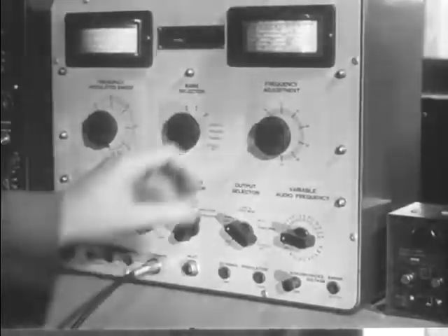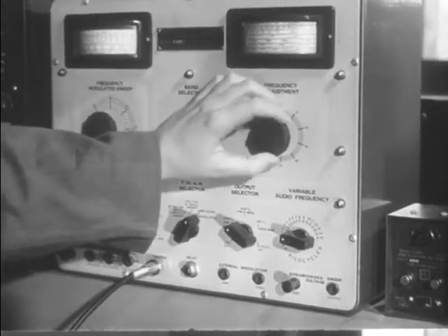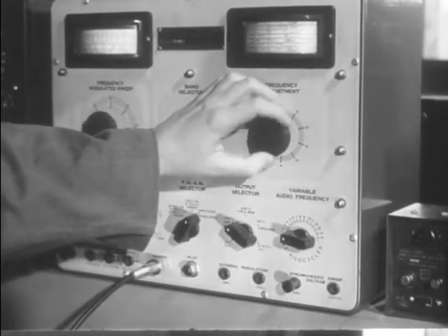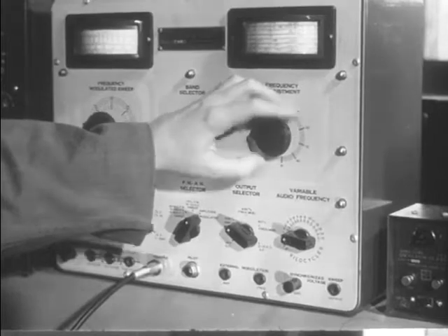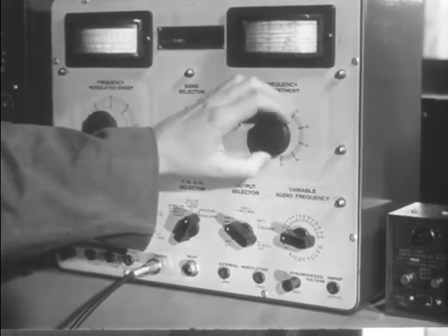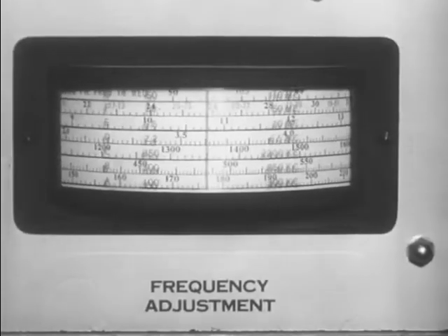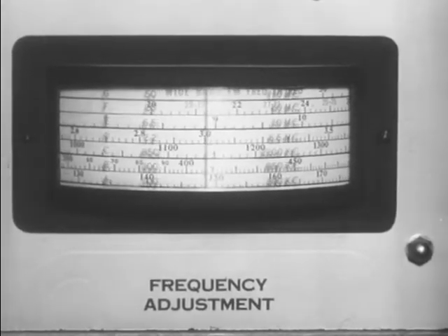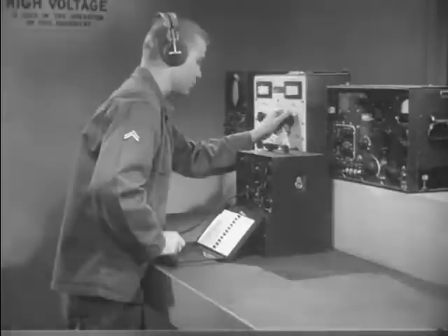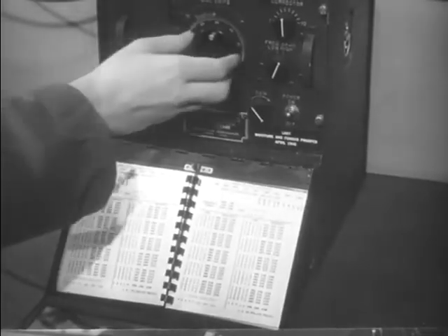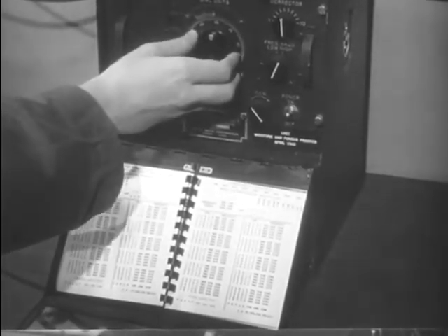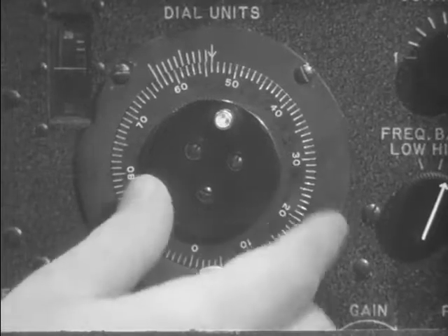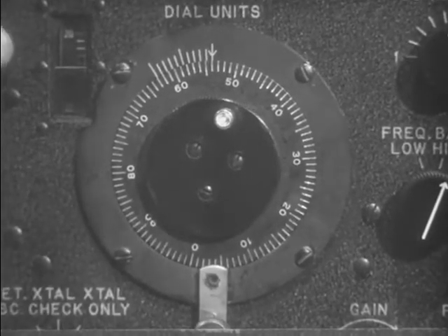The signal generator, through jarring or other mishap, may get out of alignment. A frequent check of the calibration of the signal generator with the frequency meter is advisable. It is only a matter of sending out a signal on the generator which is received by the meter. The frequency meter is tuned to the exact frequency until a 0 beat is reached.